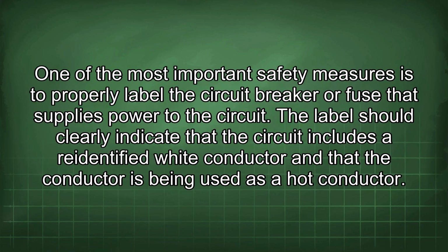One of the most important safety measures is to properly label the circuit breaker or fuse that supplies power to the circuit. The label should clearly indicate that the circuit includes a re-identified white conductor and that the conductor is being used as a hot conductor.